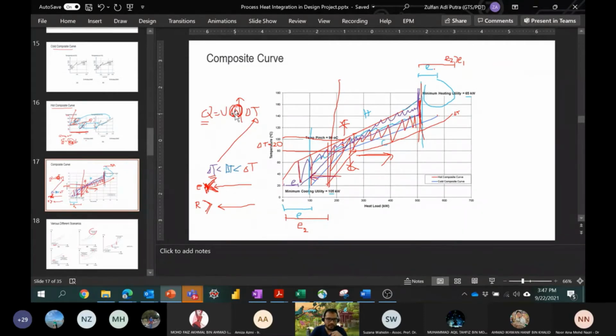Because we need to recover heat as much as possible, comparing the cost of the compressors, we can pay for more heat exchanger area instead of bigger compressors. Hence they tend to use a much lower delta T, like 2 or 3 degrees C.